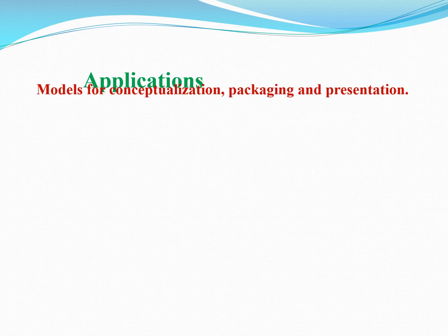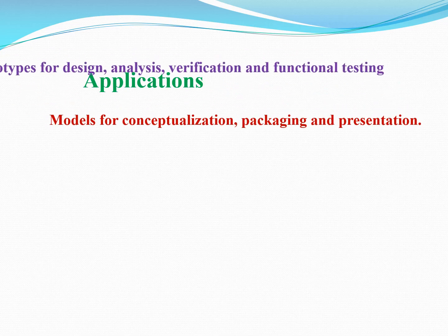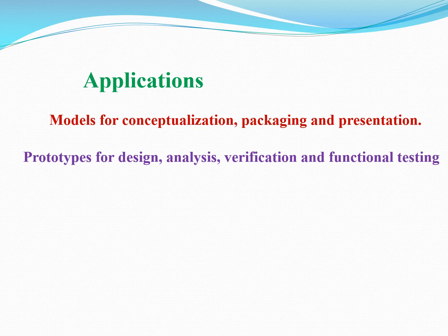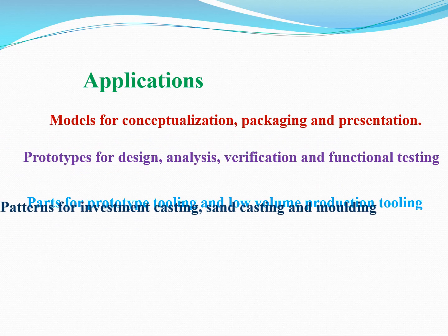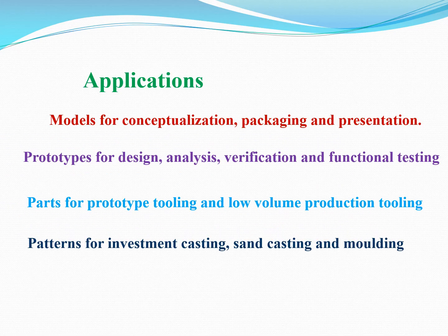Now the applications: models for conceptualization, packaging and presentation, prototypes of design, analysis, verification and functional testing, parts for prototype tooling and low volume production tooling, patterns for investment casting, sand casting and molding. So these are the wide range of applications of this process.